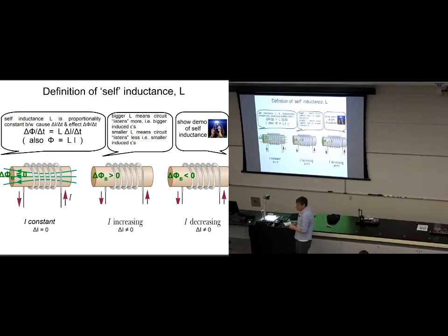As I say, the bigger the self-inductance, the more the circuit talks to itself, the larger the induced EMFs you'll get when you switch the circuit on and off. The smaller the self-inductance, the less the circuit talks to itself, the weaker the induced EMFs you'll get when you switch the circuit on and off. I want to show you a demonstration of this too. It's not going to be very dramatic after this one.